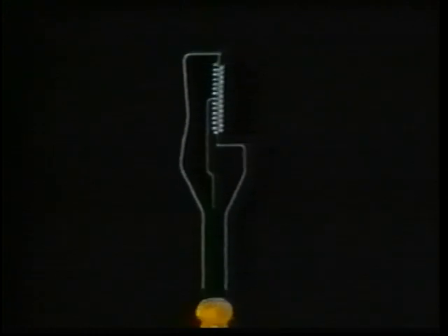Lead-in wires supply electricity to the filament. They incorporate a fuse at the bottom to protect the lamp from overwattaging in case the lamp arcs. A mount structure supports the filament so that it will maintain its proper shape. A stem press provides an airtight seal around the lead-in wires, and the exhaust tube is used for evacuating the air from the lamp and refilling it with the proper gases. All around this structure, the bulb, made of either hard or soft glass, depending on the final use for the lamp, provides the proper atmosphere for the filament and seals it from the outside air.